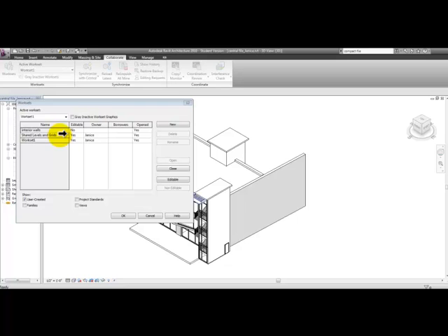central file. To create a central file, save a file to the network folder, or one that everyone can access. Then pick Worksets in the Collaborate tab to enable work sharing, which cannot be undone. Once the file is created as a central file, you can then save it as a local file.